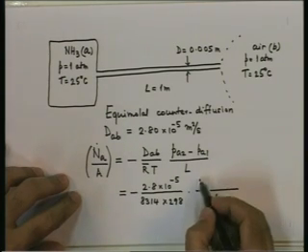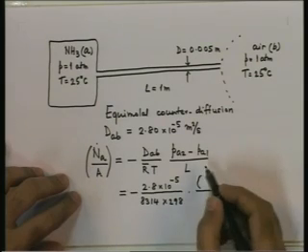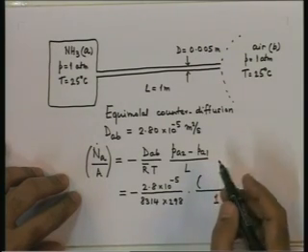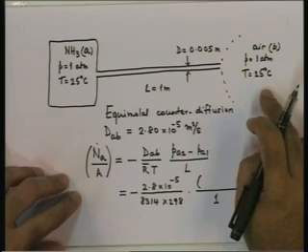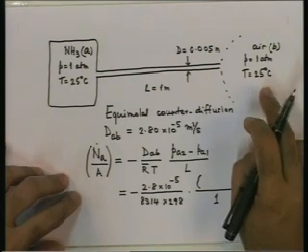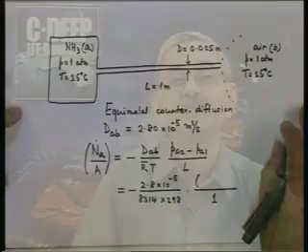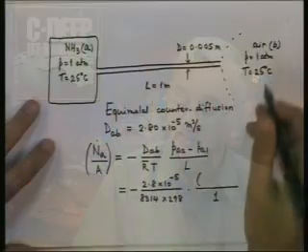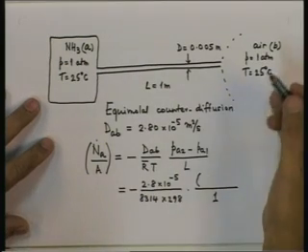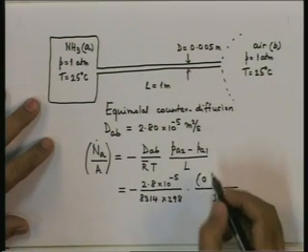In the numerator, we have the pressure difference. Let us assume that there is no trace found of ammonia vapor in the atmosphere. The atmosphere is a large reservoir. Whatever ammonia leaks in gets dispersed pretty fast. That is an assumption. So, the partial pressure of ammonia in the surroundings, that is effectively reservoir 2, will be 0.